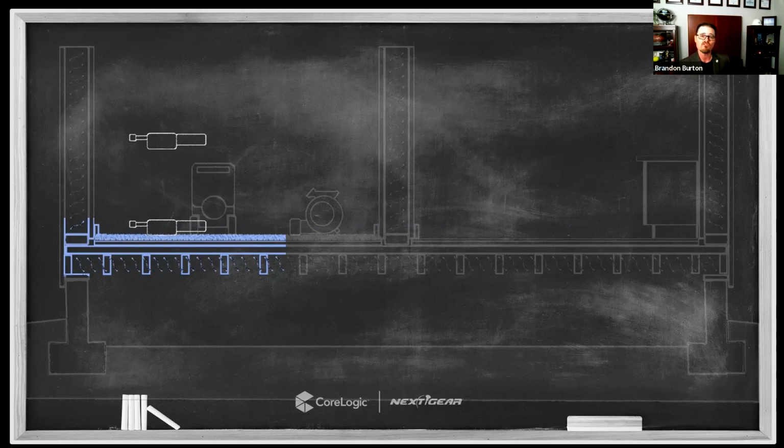So a secondary measurement that's really critical is, once you know what's happening up here at chest level, I need to find out what's happening down at foot level, right? What's happening right down there at the surface. And if there's any significant deviation there, if the air above is much warmer and drier and the air below is much cooler and wetter, your air movement installation has failed, right? And that's really how we validate an appropriate installation of air movement. It's not by taking one hygrometer reading, it's by taking multiple hygrometer readings and comparing those readings for any deviation.